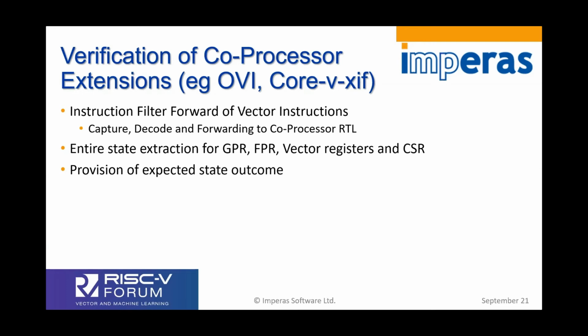Now, the difficulty this customer has is that they do not have the entire RTL system in place. This means they cannot write RISC-V programs for directed testing, run any of the compliance suites, or use a random instruction stream generator. There is no fetch unit, execution unit, instruction pipeline, or any other components which are necessary to execute instructions and forward the vector instructions to the vector unit.